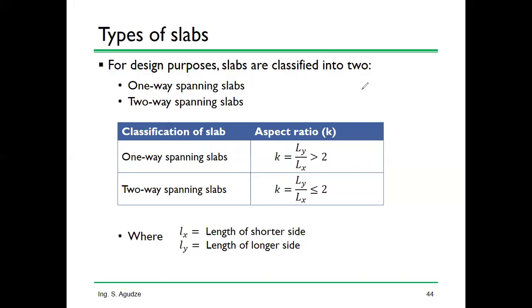So in terms of beam slab system, we are talking about a structure made up of beam, slab, column, beam, slab, column, beam. That's the common one we have in Ghana. So if you have the beam grid like this, this beam divides the beam here. So the slab defined by this is a panel, we call it slab panel. I think I showed you last time when we met, slab panel.